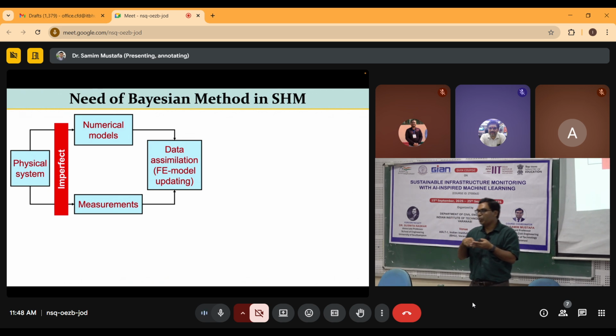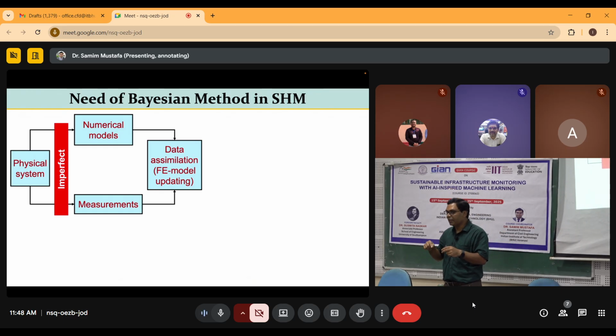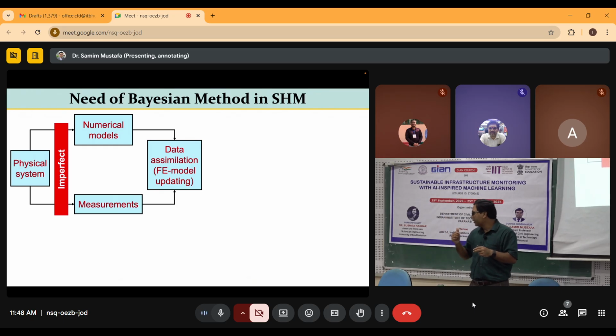Then there could be deviation in reinforcement, because theoretically I am giving the reinforcement like this, there should be some overlapping, and another kind of extra reinforcement should be there. But at site, it could be possible that it is not implemented correctly, okay, to minimize the cost by the contractor. Then there could be a discrepancy between the design and the actual implementation.